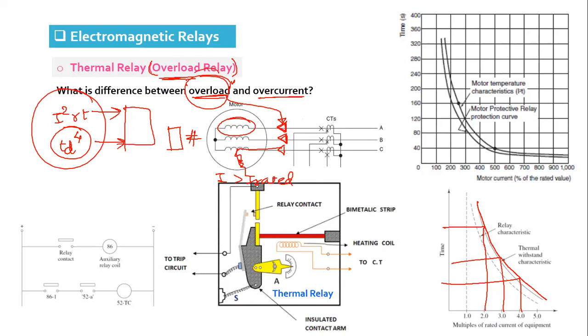But when the equipment is overloaded, the heat generation will be at a higher rate, and that is why the equipment will be subjected to an overheating condition, mainly the insulation around the winding. This insulation has a limited capability to carry this overheating or temperature rise, and after a certain time the insulation may deteriorate and fail, which may result in a fault.